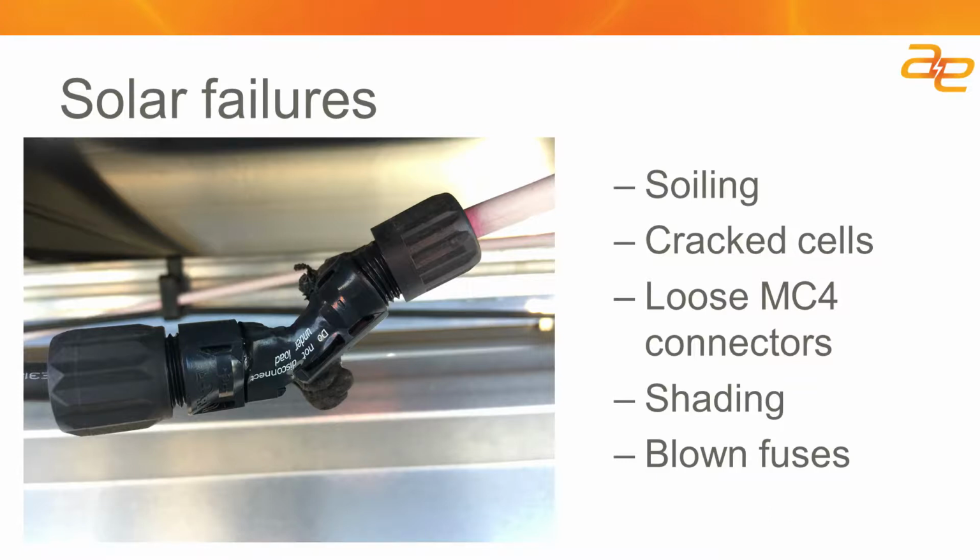You get relatively consistent soiling across all the modules, but at the same time, during the construction process, it's not uncommon to have a big blob of oil fall down on some solar cells while they're placing inverters or transformers, and that oil is not visible at the time. It's clear. It's hydraulic oil, so you don't really see it there, but it attracts dirt and it's super sticky, so that soiling in that area on one module will be persistent over time and get much worse.